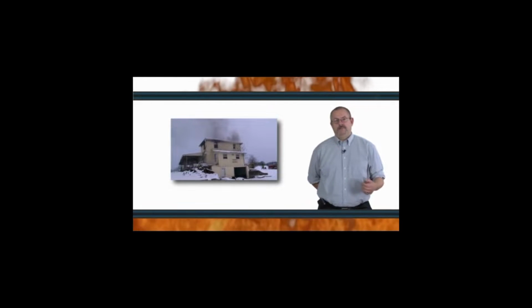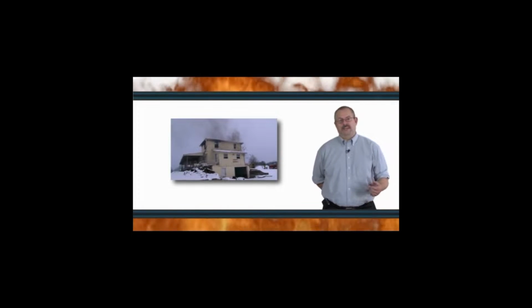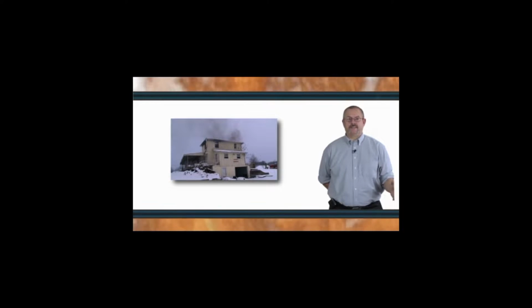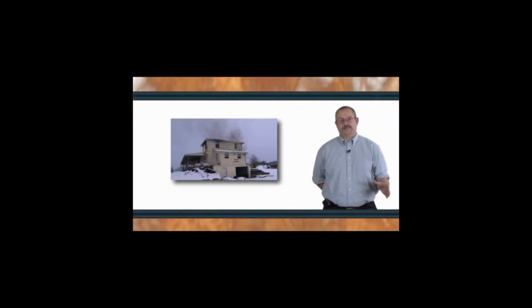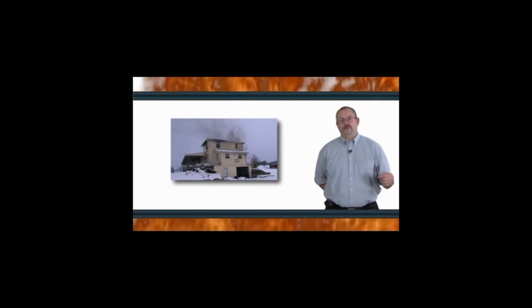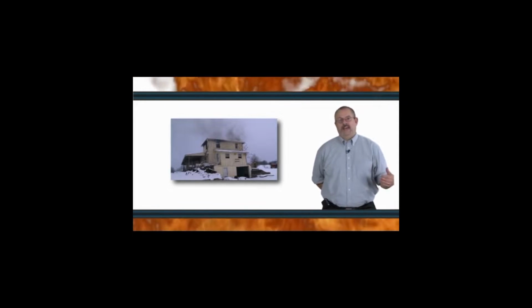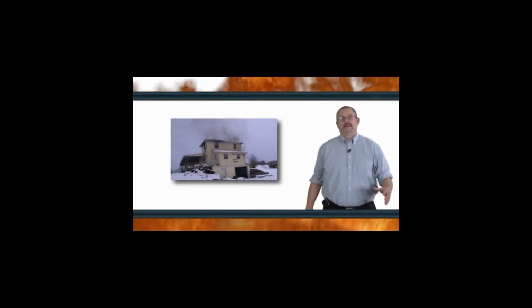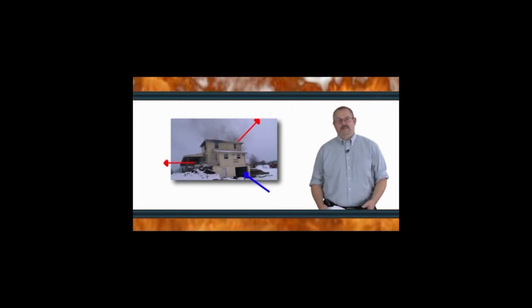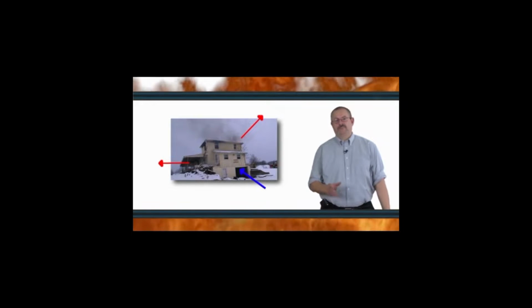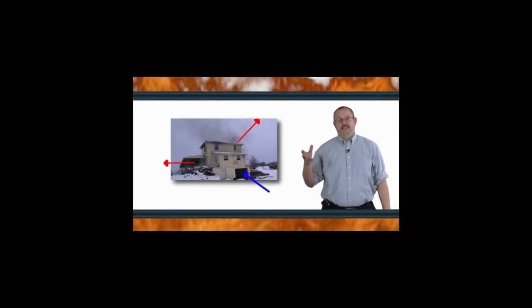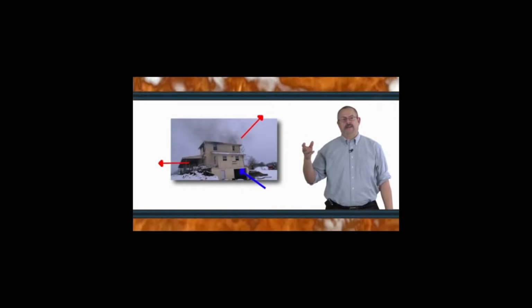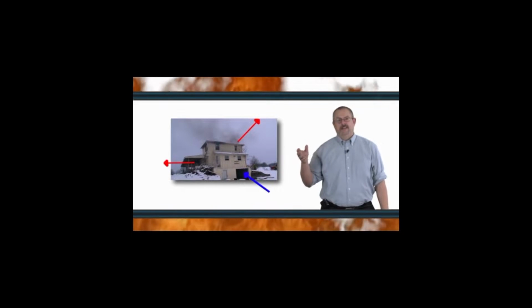In more modern construction, many basements have walkout doors, exit windows, much larger window vents, and now these set up a high hazard. If the firefighter is approaching from above, and one of those windows should be vented or accidentally break out, it would change the flow path such that fresh air is coming in low in the basement, increasing the heat release rate of the fire, and then the exhaust gases would be going up the stairs. In effect, any firefighter trying to come down the stairs is in the chimney.